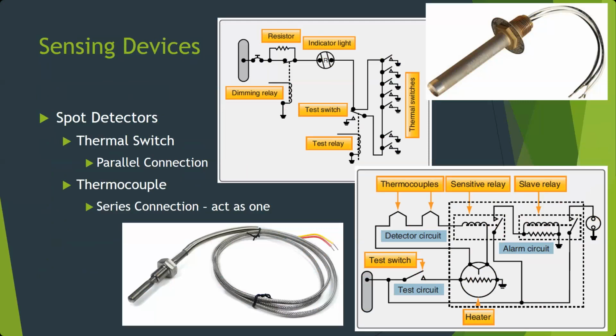Kind of. It doesn't latch though. It resets when it's done. A circuit breaker has the bimetallic strip, but then it latches. This doesn't latch. It's going to self-reset when it cools back down. You tried these on the fire board in there, right? You put the torch against the two little things sticking out, it went, but as soon as you took the fire away, it went back to normal. Not even that, I think those were like 5 seconds. The loops took about a couple minutes.